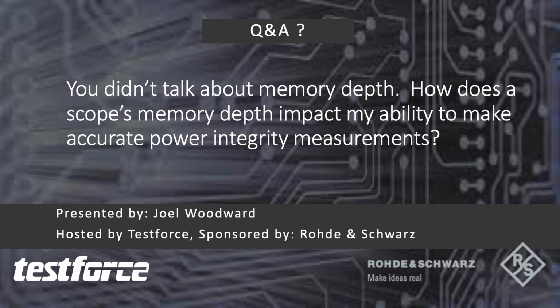At some point in time, the oscilloscope runs out of memory and it says, you know what, I don't have any more memory. What I'm going to do is drop my sample rate in half. You turn the horizontal scale again and it drops the sample rate in half again, etc. Oscilloscopes that have deeper memory are more capable of enabling higher bandwidth over those changes to slow time bases.